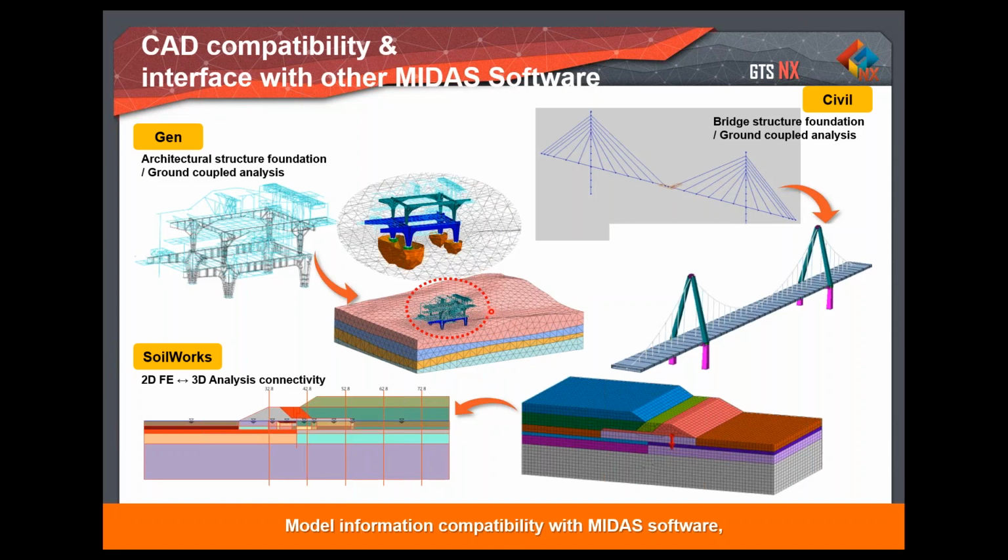So I dig the soil in different stages. After digging, at each and every stage, there would be a settlement, which might be a differential settlement, posing a very great impact on your existing structure, which should not happen. So we need to go for stabilization techniques like provision of secant piles or sheet piles, and all the different techniques. Even that can be directly modeled and analyzed using this particular software.